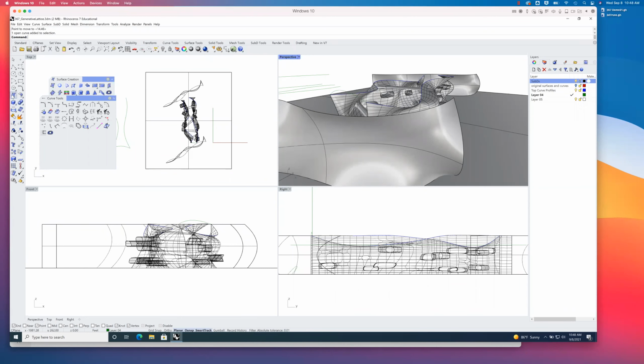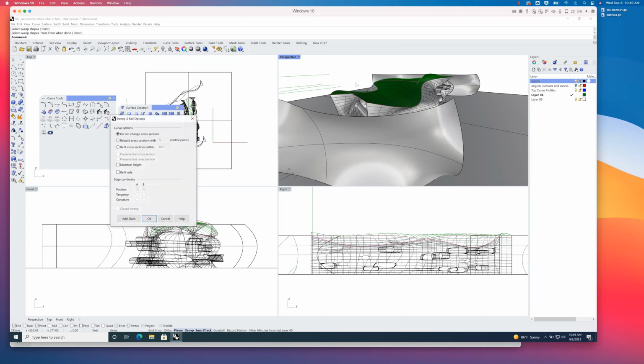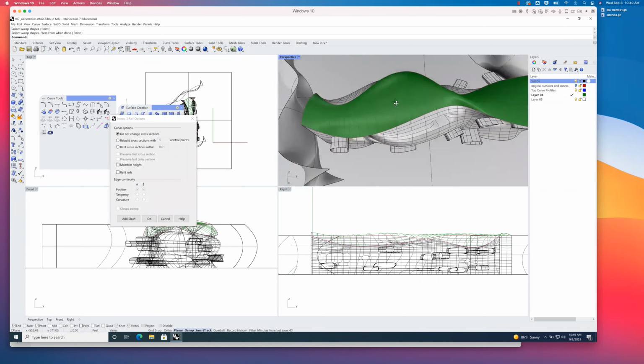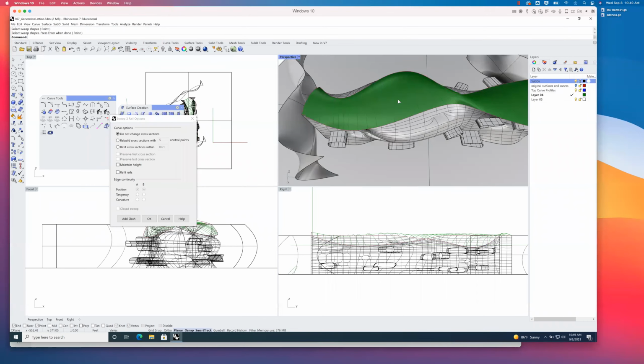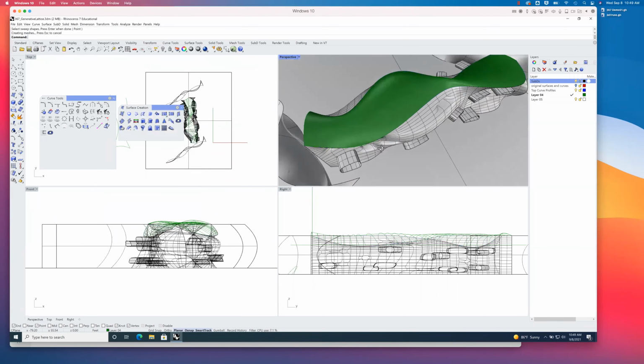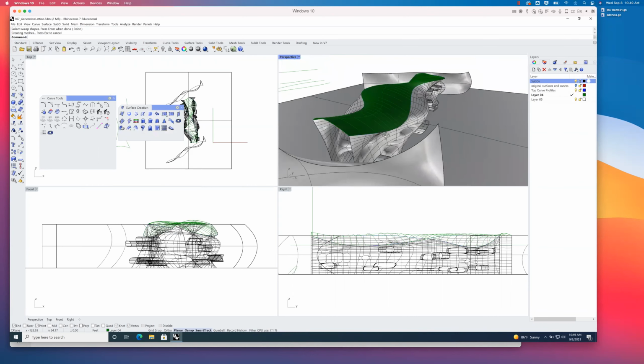All right, so let me try that here. I'll try this in Rhino first. Sweep 2 rails, select the first rail. Okay, select this one. Select the second rail. Go ahead and select this one. Now select any sweep shapes. I can select more than one. I'll just go ahead and select this one because I only have one. I'm going to right click to hit enter. All right, there's a surface. Excuse me. Whew. I'm going to go ahead and hit OK. All right. There we have it.